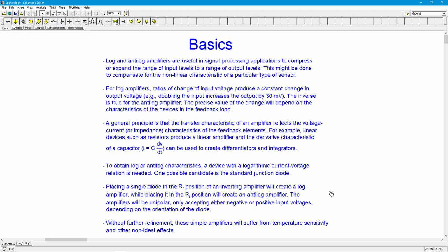When you throw in a particular diode model, if you use multiple diodes, they're all exactly the same. In the real world, matching your devices is an issue. So if you're going to use something like a bipolar transistor, you can buy matched pair transistors, and that will help you. But again, I'm just going to stick with these simple introductory diode circuits.